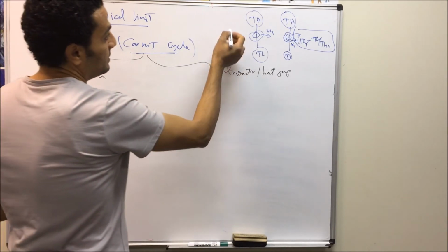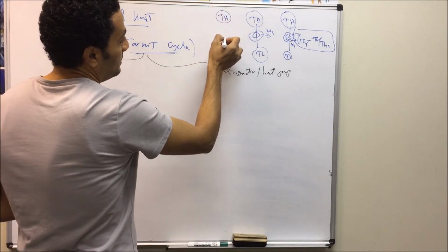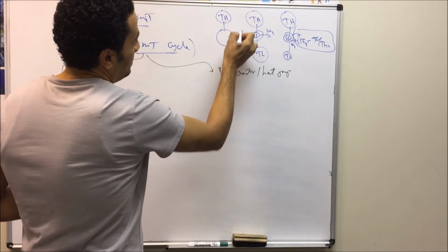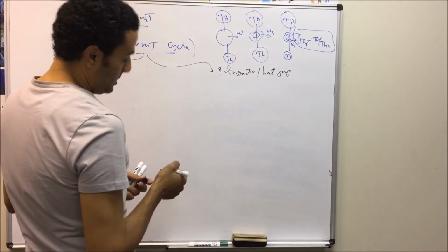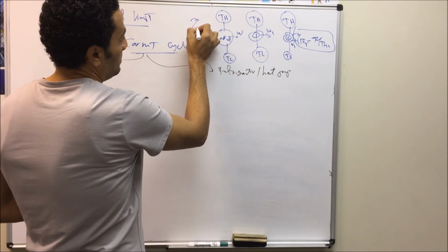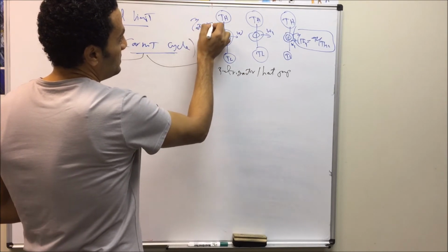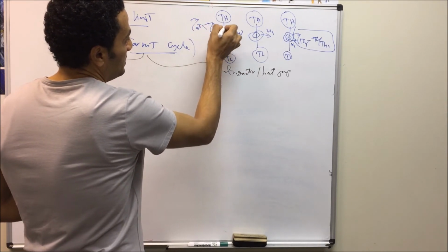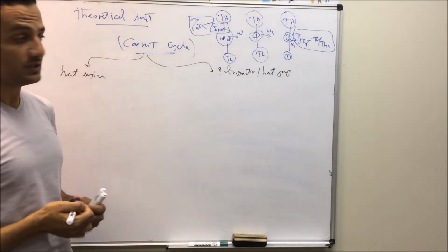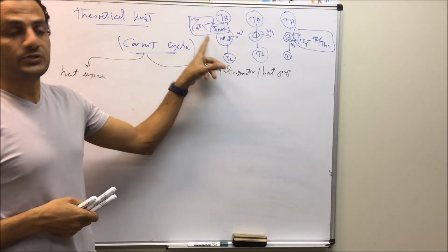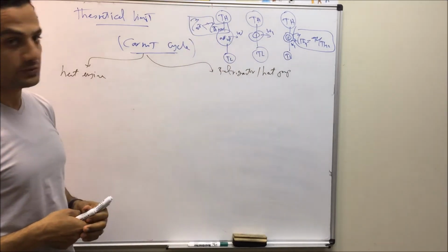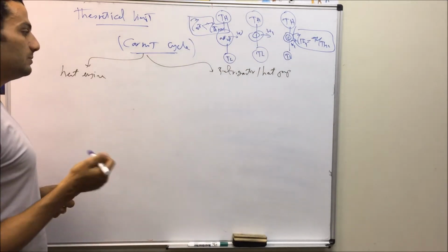Also, if you do have two heat engines, one reversible, between T high and T low, with work out, and the other an actual heat engine, the efficiency of the actual engine should be less than the efficiency eta thermal reversible of the reversible heat engine. And this is logical. In case of an actual heat engine, we do have losses, so its efficiency should be less than the reversible one, where we don't have losses within the system.